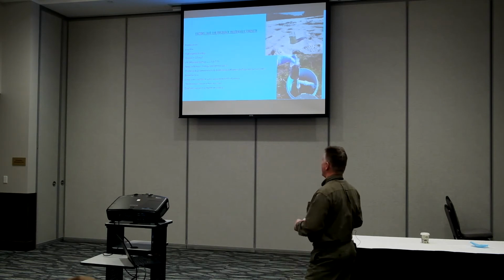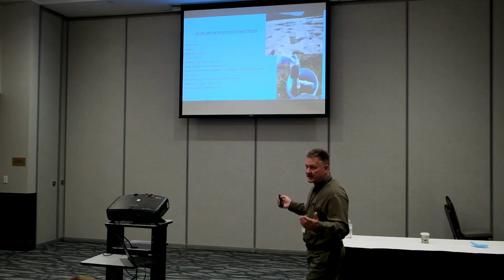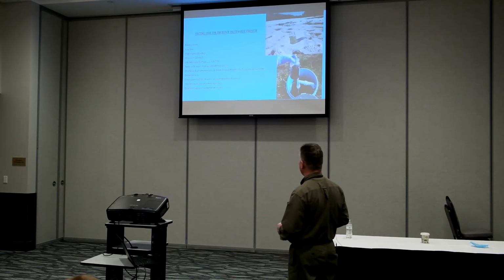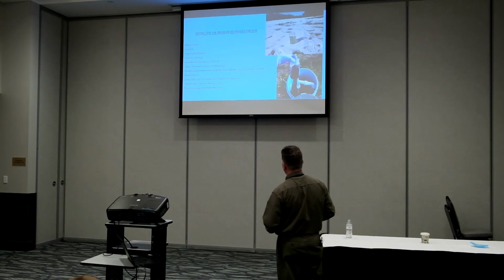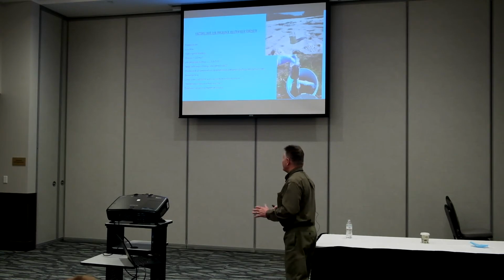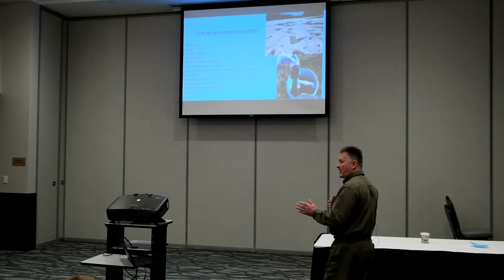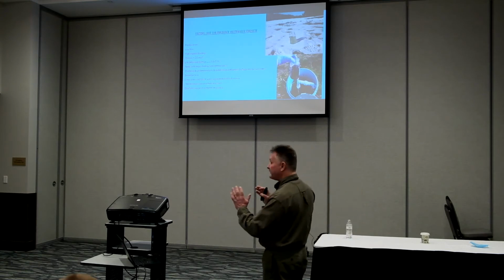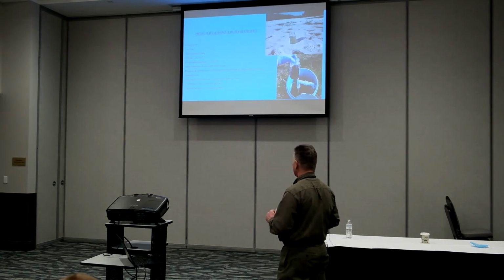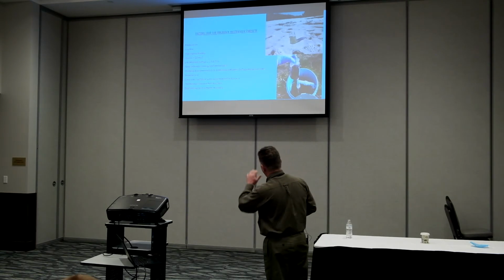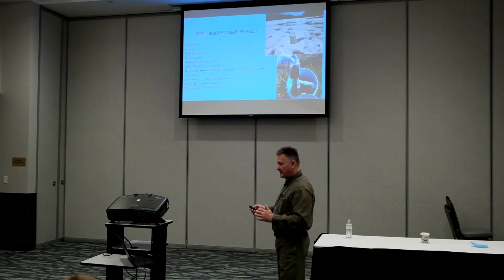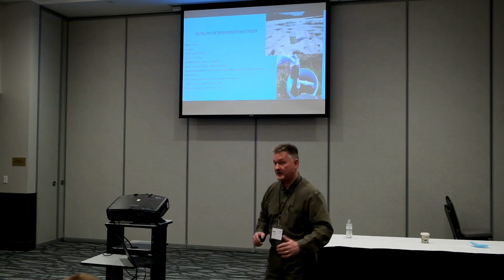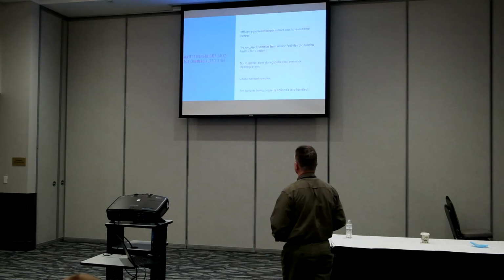Lack of detention time. That's pretty obvious. If you have an undersized tank and the flows are getting through, we're not going to get the degree of treatment that we need for our primary treatment. So we can consider separating the gray water from the black water and dealing with it that way, getting a little more detention time, for instance, for the grease tanks. I already mentioned the collection system. We should be paying attention to various processes, making sure they don't have a detrimental effect on the outcome going out to our system.